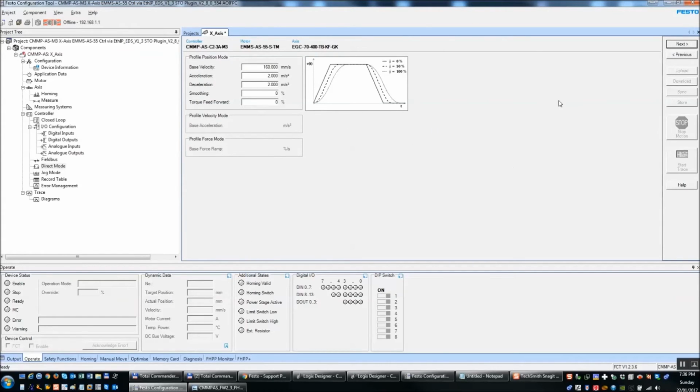So in direct mode, so in direct mode position, you have the ability to send the position target and also the velocity. The velocity is expressed in a percentage, 0 to 100, and that percentage is based upon this value right here. So if I make this 1,000 and I specify 50%, then it'll be 500 millimeters per second that the move will take place at. The accel and decel are set in stone here, so all moves will take place at the values that are shown here. If you want to modify the accel and decel later, then you get a little more advanced.